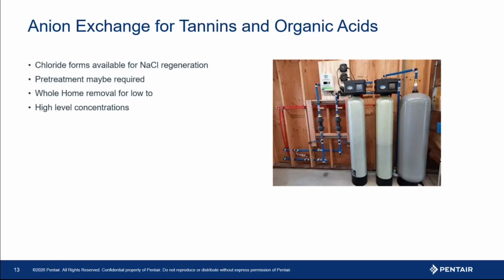Make sure you're sending water analyses to OEMs about your waters with color. That may be a challenge for you, so you can get their best input and look at different technologies so you can design the lowest cost version of a treatment train for that specific water.